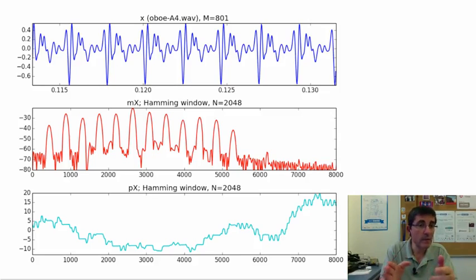Here, because we took more samples, the distance that we can now discriminate is smaller. In fact, we see that the main lobes are narrower than what we even need. We even see the side lobes in between the two main lobes because we took a bigger window size, and therefore we are able to discriminate even more than the fundamental frequency.